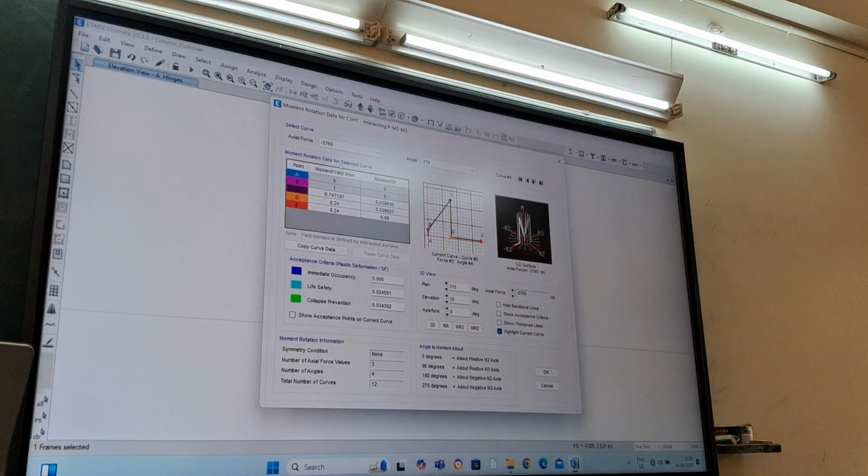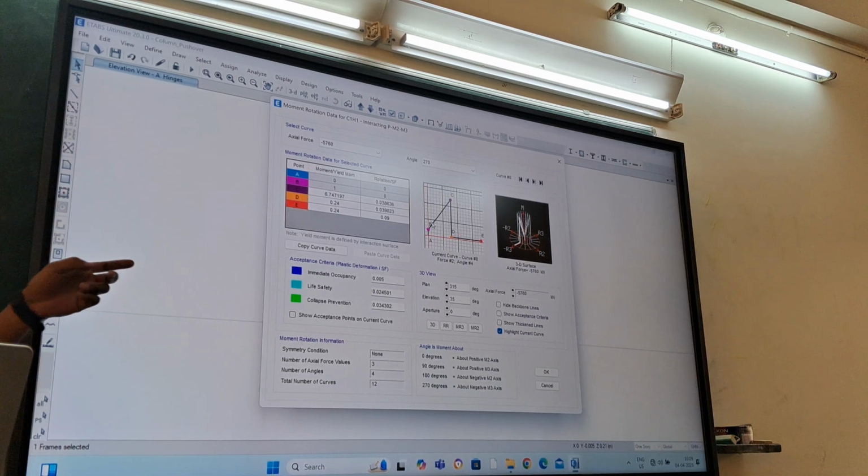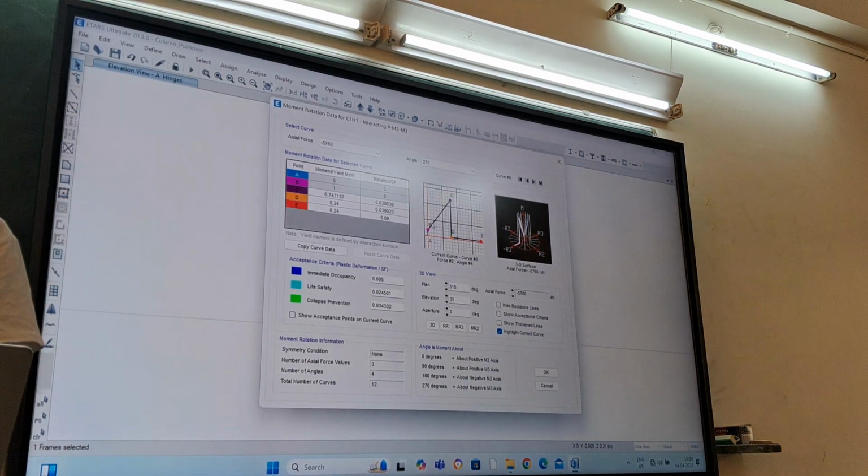Okay, Sir, this is the lumped mass method. Yeah, lumped mass method. That's why it is showing that. Yeah, backbone, that's why this is a load deformation curve. This is similar to what you see in SC41. Maybe the shape differs, after yield point the strain hardening is steep here. You can change this here, but we will not do this, leave it.